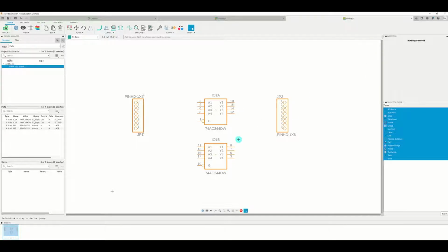So you have that. Okay, so let's try connecting these pins to the pins of the IC. To do that, you have to use the connect. In the connect you can make use of this net, not the line, you have to use the net, so there'll be actual connection. So click the net, and then you can select the type of net that you want. You can have straight, you can have bend, and so on. So let's try the straight one with a 90-degree bend.